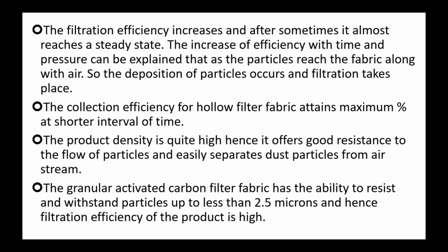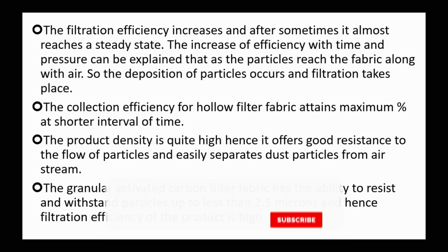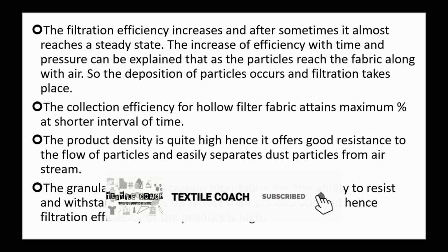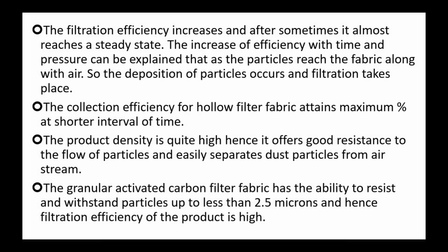The product density is also high, and it offers good resistance to the flow of particles and easily separates the dust particles from the air stream. These features are provided by the granular activated filter fabric that I have employed in the intermediate layer. It has the ability to resist and withstand particle sizes of less than 2.5 microns, and hence the filtration efficiency of the product is very, very high.